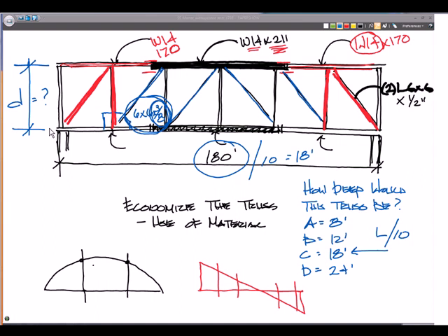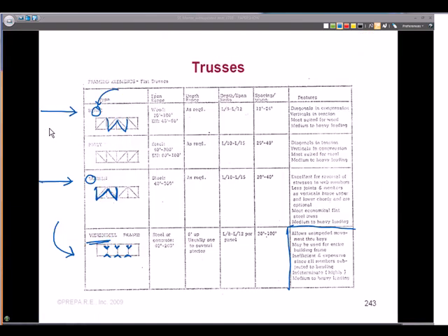I would say 12 would be pushing it. Once you're in the 10 to 12 foot range, you're spanning about 100 feet or 120. So to go another 60 feet, you may have to post-tension or pre-stress the truss if you have that, and some of you may have done that on your job. And that's why, with the span to depth ratios, I think the Architect Studio Companion and some of these other articles like this one here give you the best guidelines so that you're not skewed by this, because somebody may say, Mark, I just spanned 180 feet with a 12-foot truss, and depending on where you are, you may have done that, okay, depending on how they reinforced it and so on.